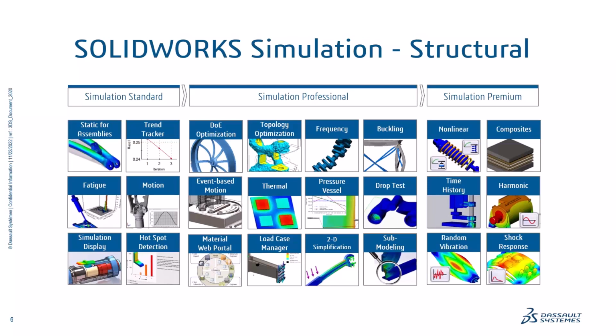At the highest level, it's kind of the example I showed you a minute ago, is where we get into the more niche things. Nonlinear studies, linear dynamic and nonlinear dynamic studies. Very easily, this adds composites to anything as well. So if you're running carbon fiber, you want to do fiberglass layup, simply the ability to do composites, even in a linear static, is Simulation Premium.